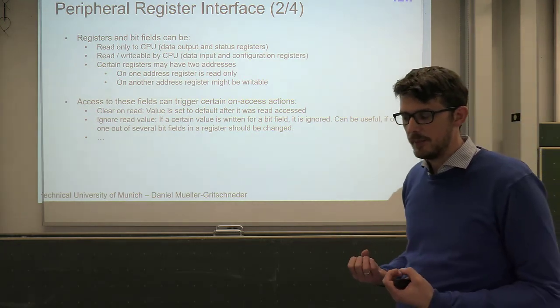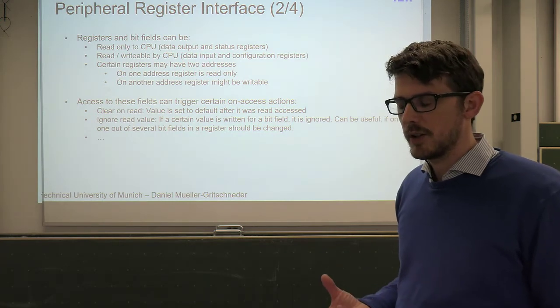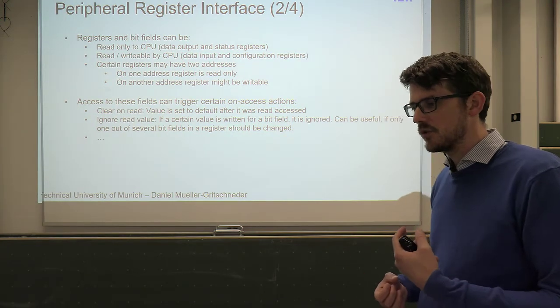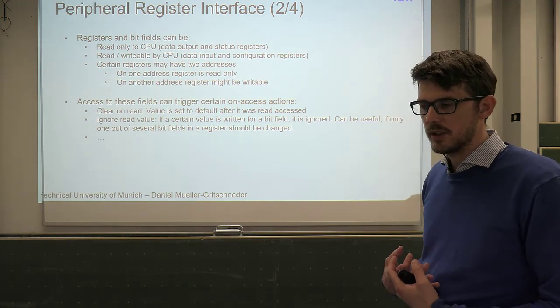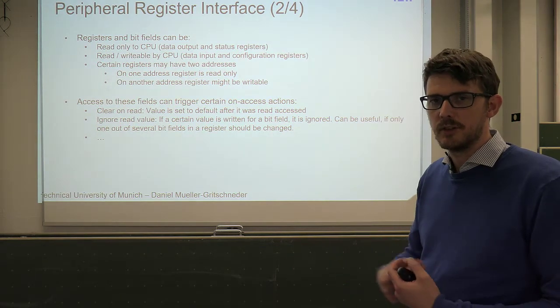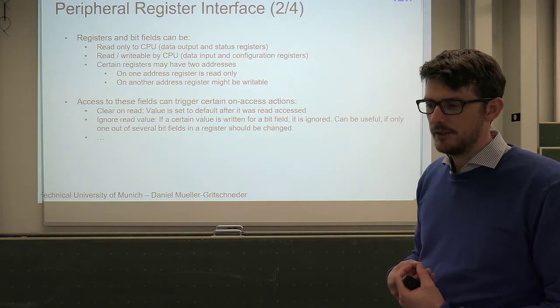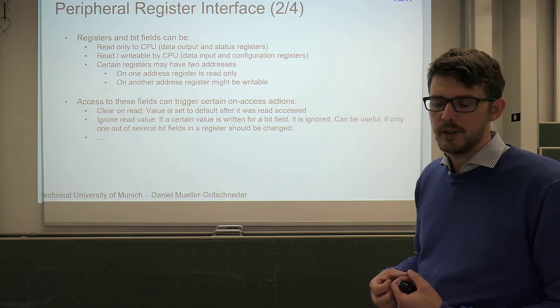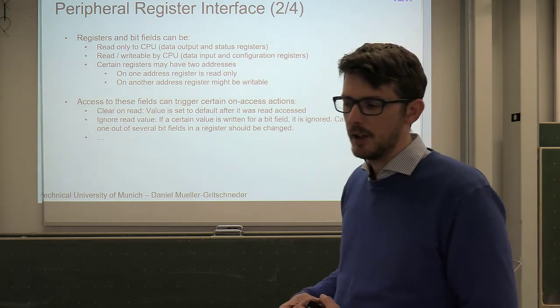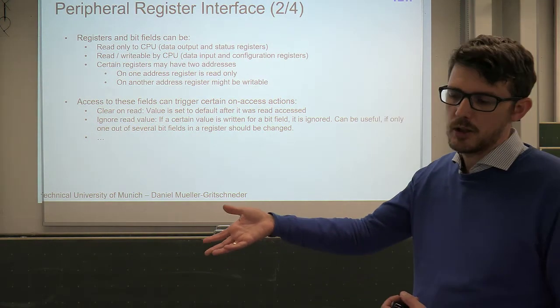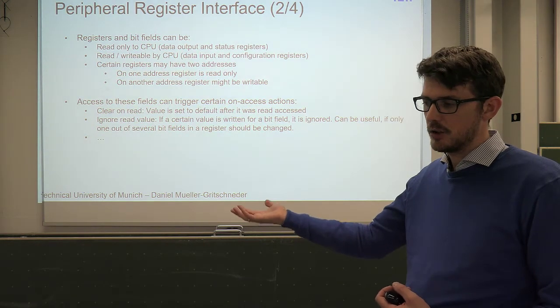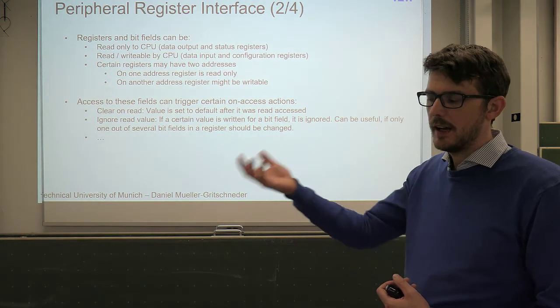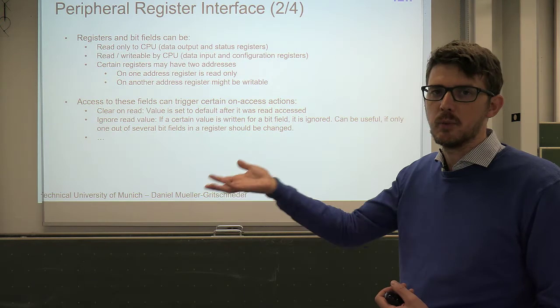Others, when you have a configuration, you want to write to it, so this might be a read-writable register. And what is also happening, but we don't have to go too much into detail, is that sometimes even just reading or writing to the register will already trigger some reaction of the device. So for example, if the device gave you an interrupt and you want to find out what the ID of the interrupt is, you might read a certain status register, which is the interrupt ID register, and then after reading it, it would already clear it right away to 0.